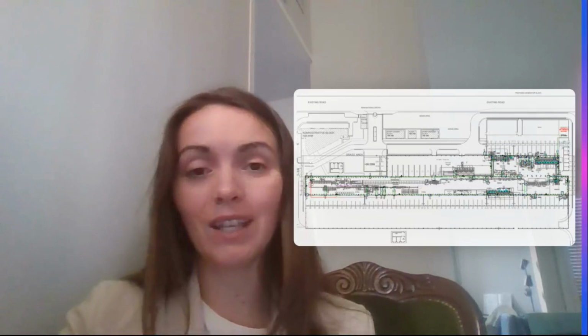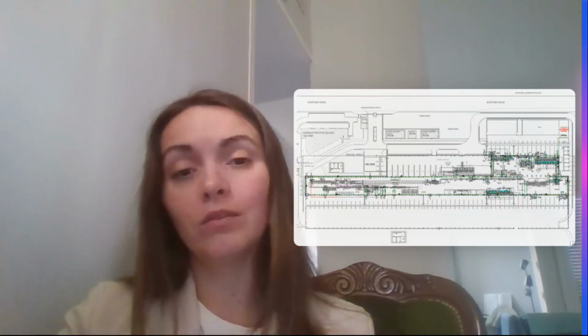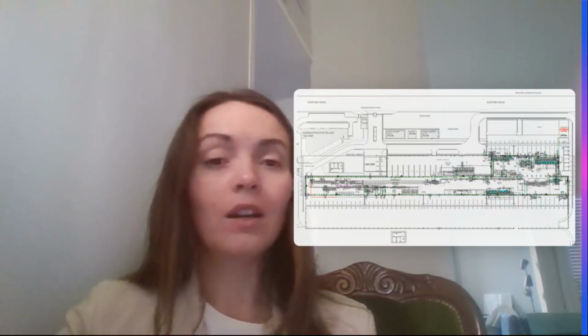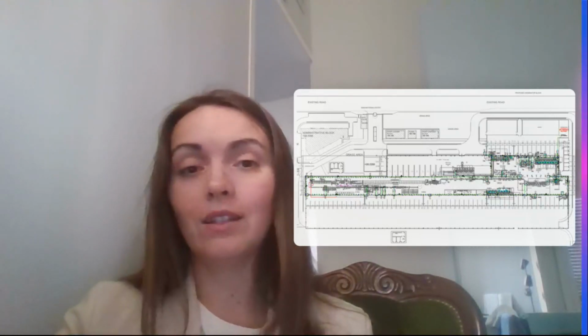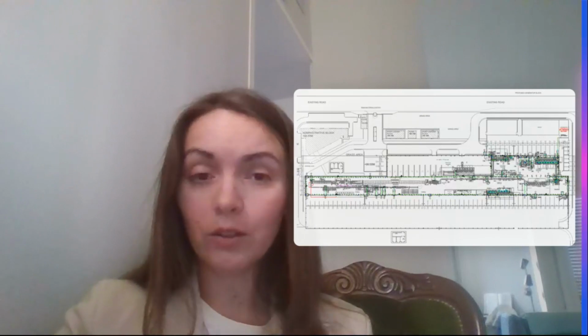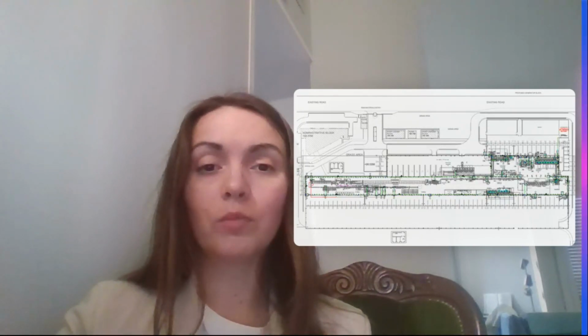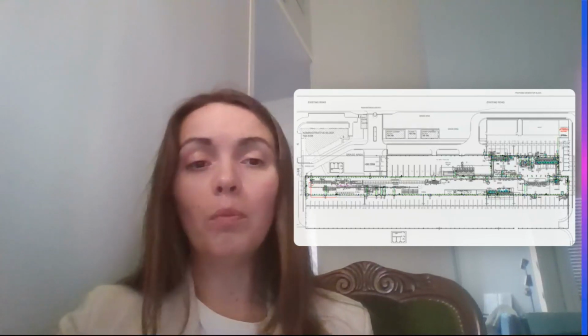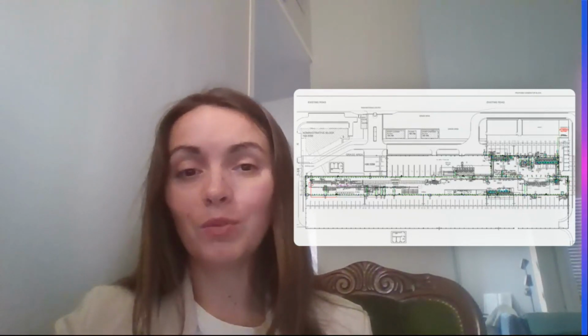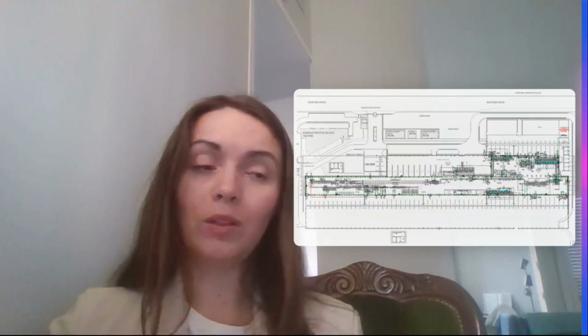This was just the understanding before the compressor room, but we have many other restrictive components, filters, regulators, dryers, of course, and the air reservoir that also has a certain pressure drop that also has to be considered in the calculations. But this is all up to you how detailed it is going to be.